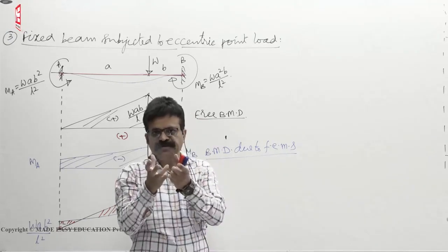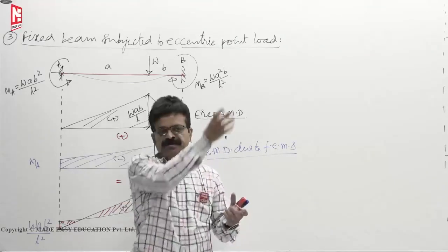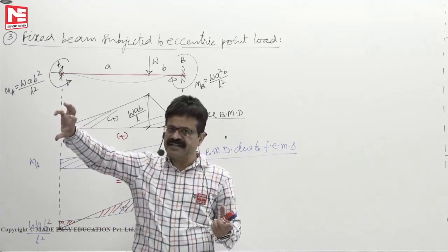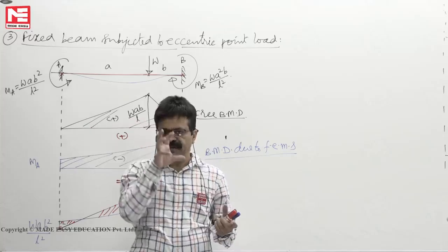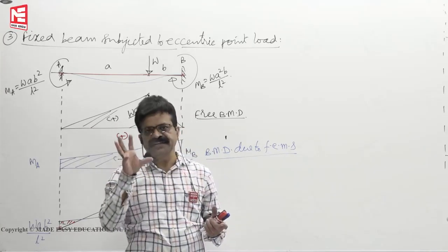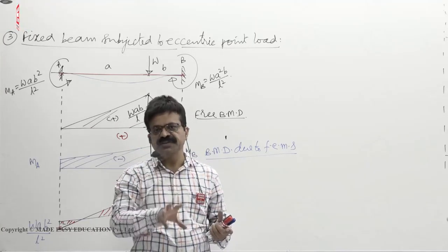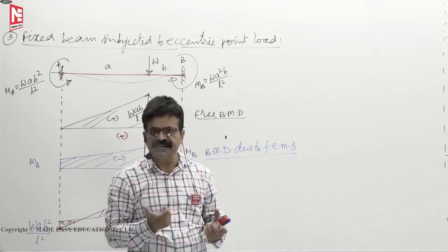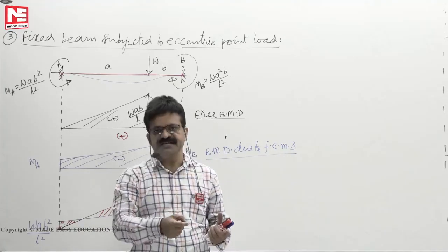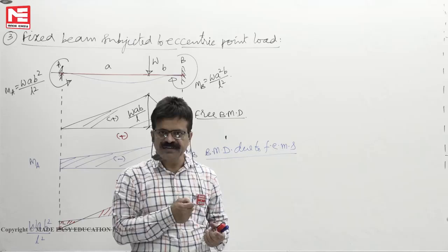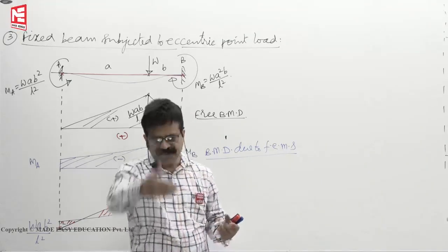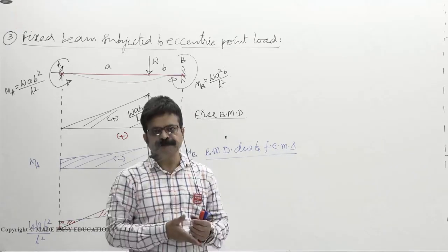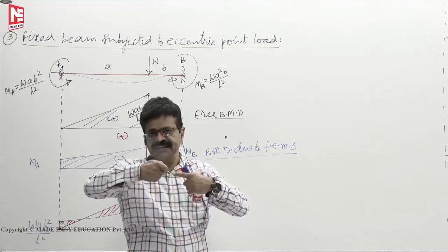Because steel and wood beams are rigidly connected and loaded, both will bend to the same radius of curvature. So radius of curvature in wood is equal to radius of curvature in steel. So from that you get bending strain in steel is equal to bending strain in wood. So one compatibility when you get it, you can analyze. Two unknowns you can find. Then wire wound thin cylinders.